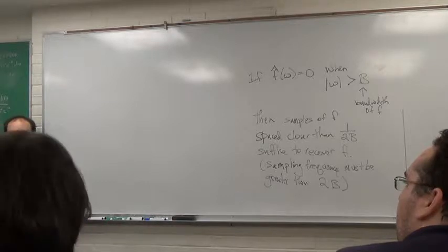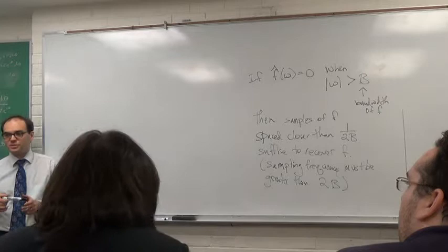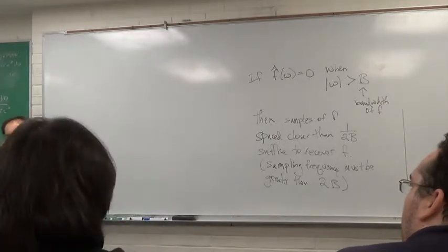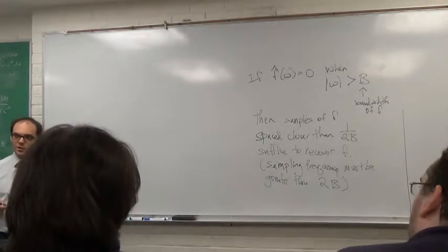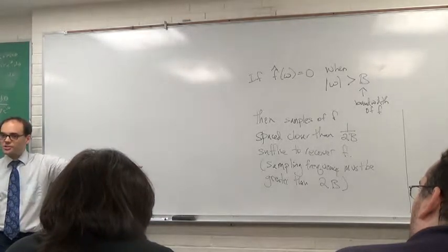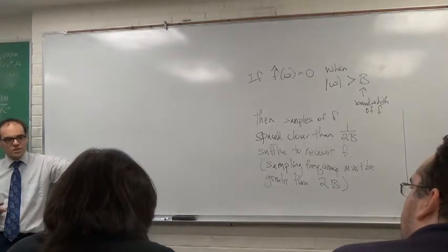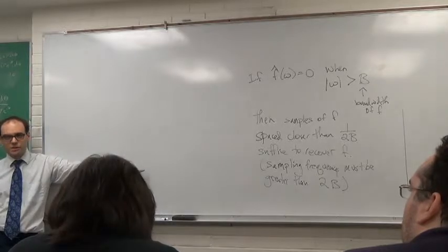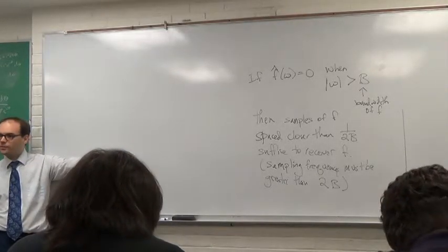No. It's about 20 hertz up to about 20 kilohertz at absolute maximum. So if I sample some music at least twice the 20 kilohertz, say 40 kilohertz, then there is no way that you will be able to tell the auditory difference. I mean, unless there are various other nonlinear effects, but just straight from recovering the signal.